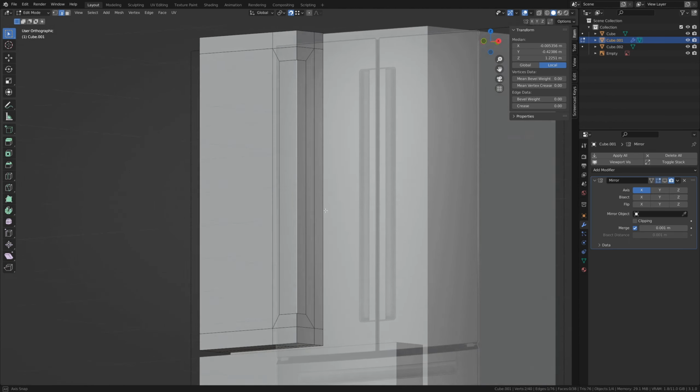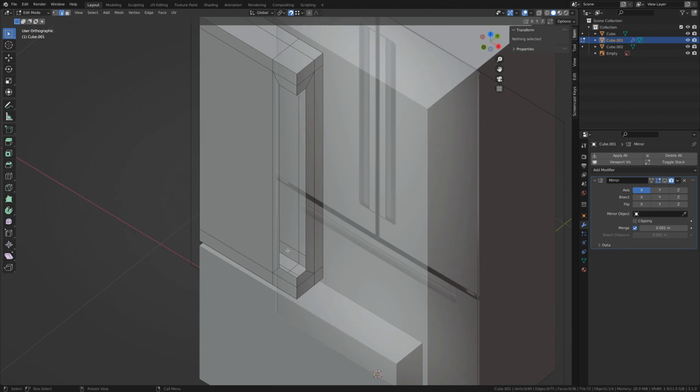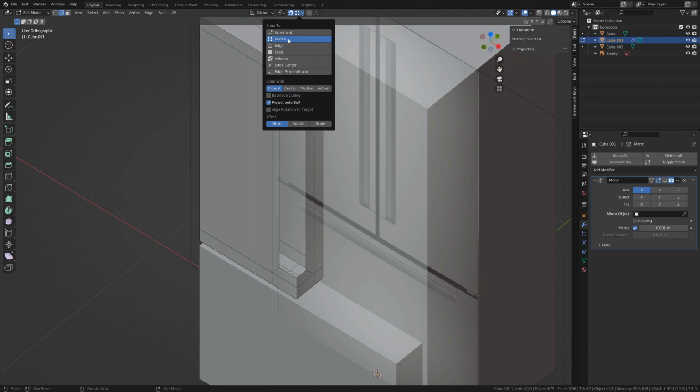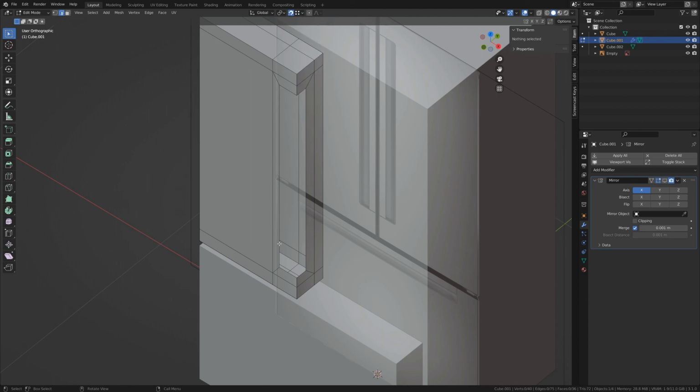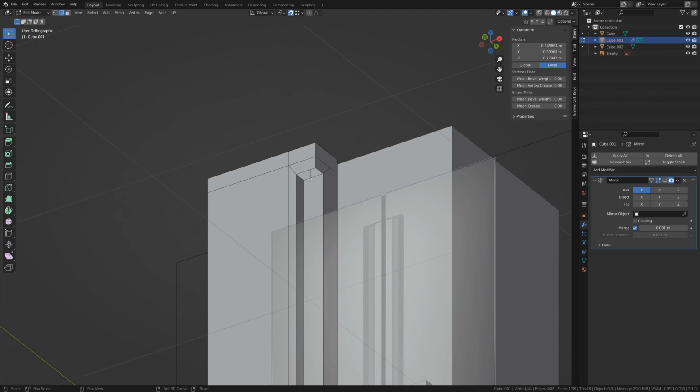So let's select that leading edge and hit delete. And we're going to delete the edges. So now we have this gaping hole. At this point we can turn on our snapping and turn it to vertex snapping. And select this edge again and extrude it on the Y only, and then extrude it over on the X. And then we can fill in these sections with the F key.